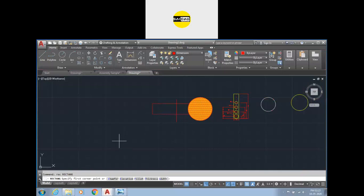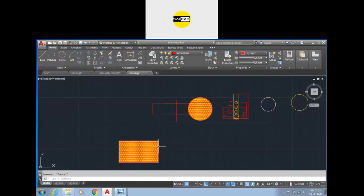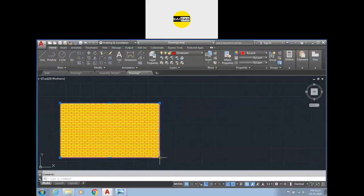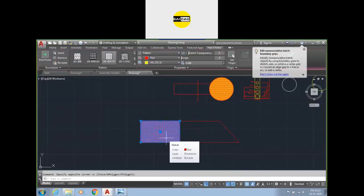Okay, if you don't create the hatch to be associative, and you select the hatch, you can see the hatch will be different and the size will be different. The shape can be changed and the hatch remains at that location.